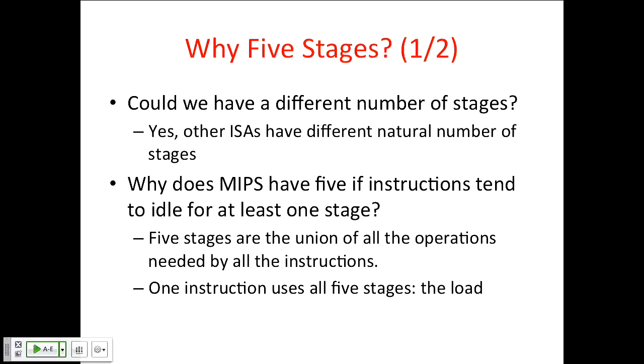For example, the adder is used to do arithmetic add. It's also used to do the address calculation. That's physically one circuit. And so we try and make all the instructions flow through the system the same way, so we don't have to replicate hardware unnecessarily. It's like an economy by making them all look the same to the system.